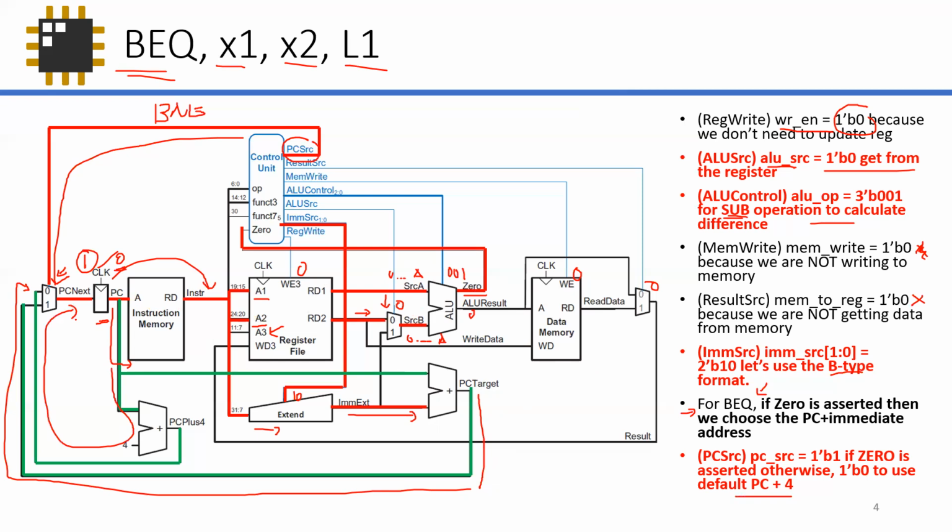It's very simple, right? So all of these are happening again in one cycle. That's why it's a single cycle processor. So the only important thing you have to take note of is that it's pretty straightforward to set which registers you have to use into the ALU. But the additional step that you have to consider is, hey, what is my 0 signal? If the branch is taken, I use the PC target.